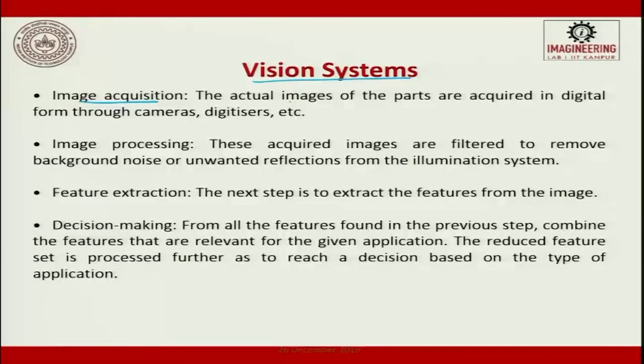So, you will use a camera to acquire the real time data, whatever it is. The actual image of the part is acquired in digital form through a camera or digitizer, etc. Next, the acquired image has to be processed. So, in image processing, these acquired images are filtered to remove background noise or unwanted reflections from the